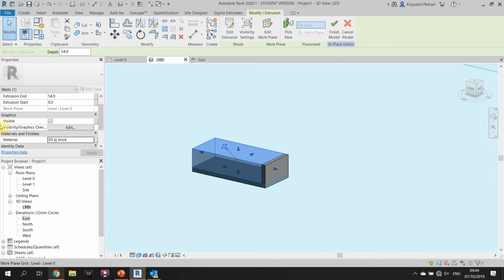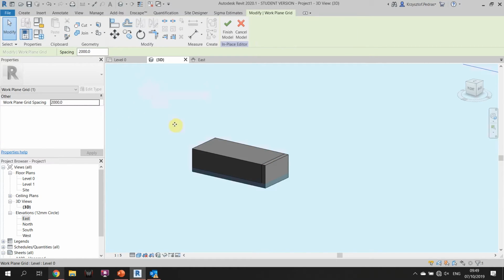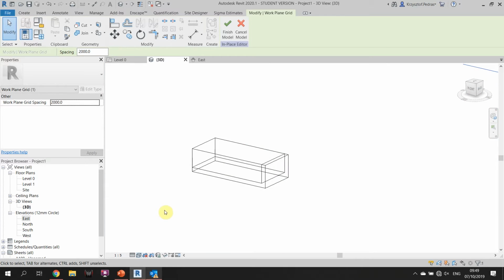and you can see that the material we created is applied, and if we unhighlight it, I'm in shaded mode, excuse me. In here, on the bottom, you have an option, visual style, shaded with edges. If you click on it, you're gonna get a few options for how the model will be displayed. It can be a wireframe, meaning that you're gonna see through it.